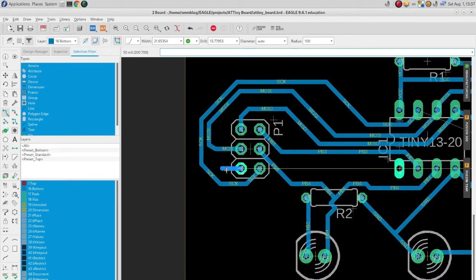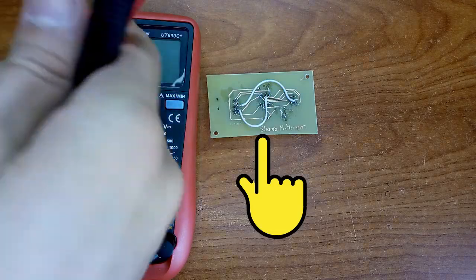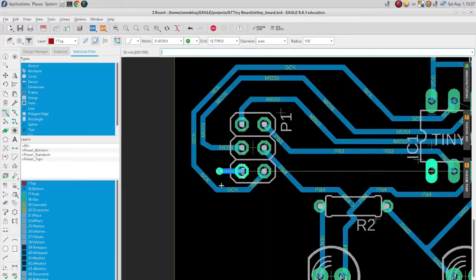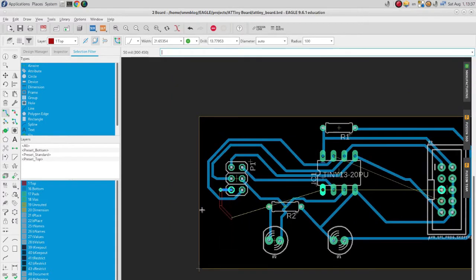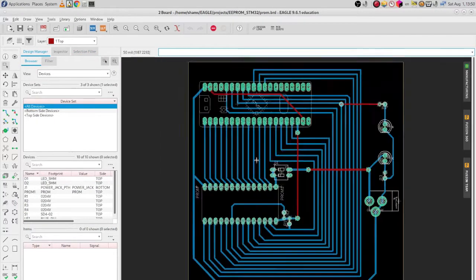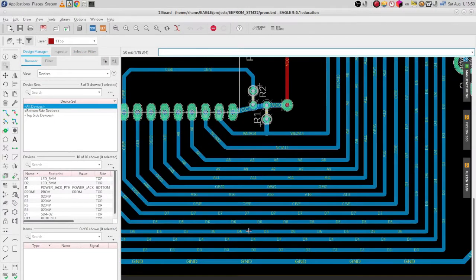Well, you actually have two options. One, just ignore it and at the end of the manufacturing, in the soldering step, just solder a wire connecting these two points. Or two, design small holes or imaginary vias where you can insert wires and solder them professionally, something like this.